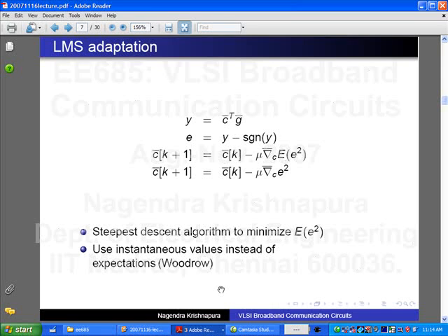Now, the thing is not just to be able to find the optimal coefficients analytically given the channel response. Because the channel response changes, you have to do it on the fly. Maybe you don't know the channel response precisely, and maybe it changes from one device to another. So when you make a chip for a particular type of channel, you are really making it for a class of channels, including some variations that are possible. So you have to have adaptation.